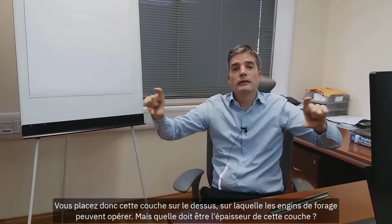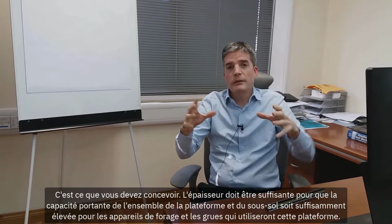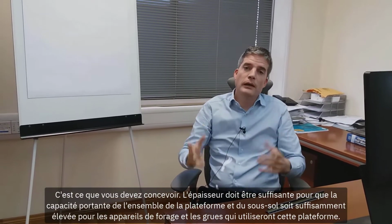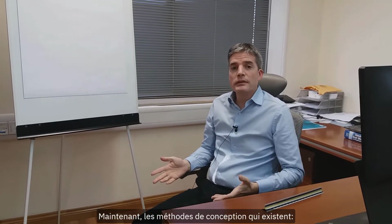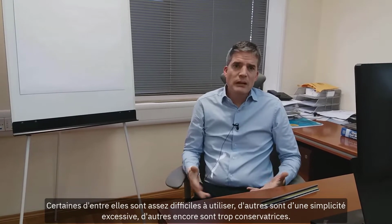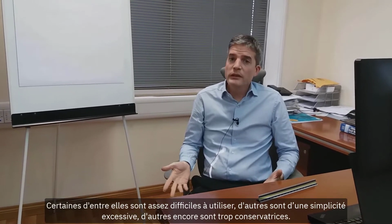But how thick does that layer need to be? That's what you need to design. It needs to be sufficiently thick so that the bearing capacity of the overall platform and the subgrade are sufficiently high for the piling rigs and cranes that will use that platform. Now, some of the existing design methods are quite difficult to use, some are an oversimplification, and some are overly conservative.